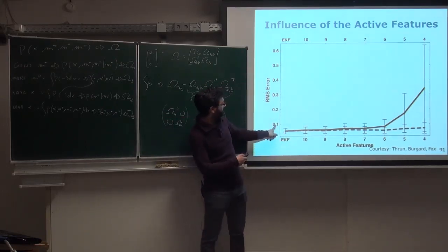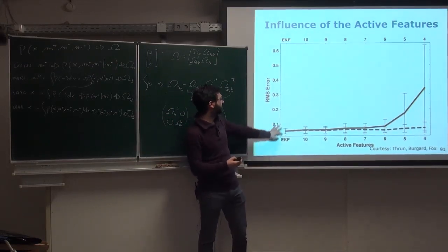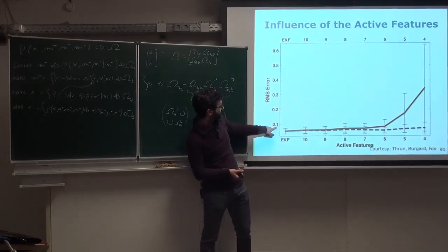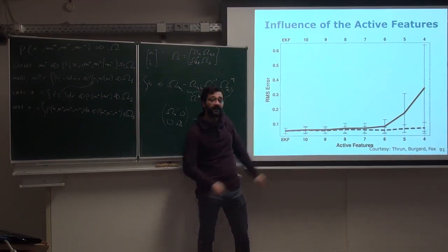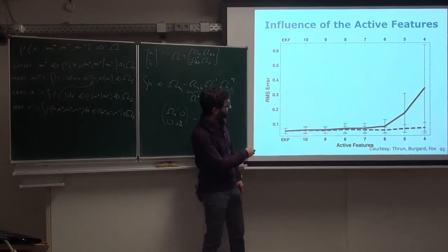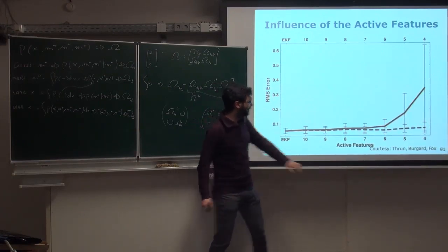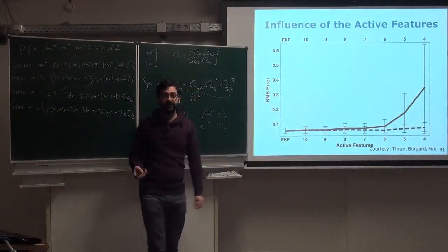The interesting thing here is the root mean square error, so the dimensionality of this is in meters when we consider translational error. You get 10 centimeters, and you see that the error is kind of negligible between the Kalman filter and the sparse extended information filter with 10 active landmarks in that particular experiment. But the fewer landmarks we take in the active window, the worse we get. And at some point, this will just blow up exponentially when we consider only one landmark, for instance. So there is always a trade-off with accuracy.